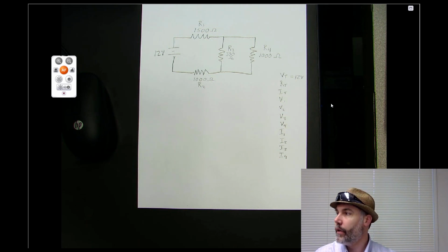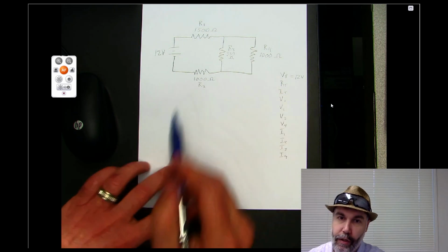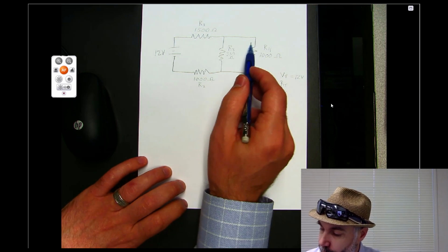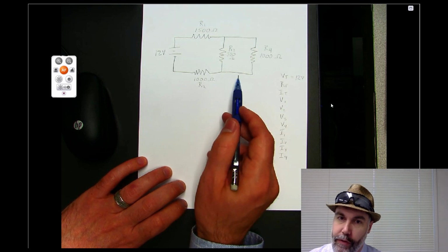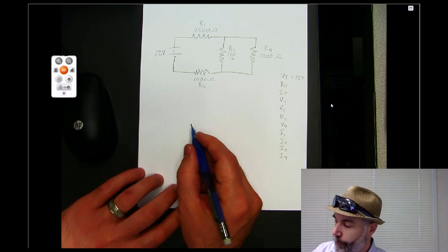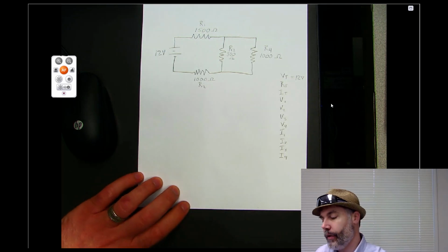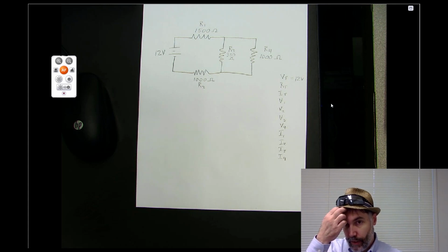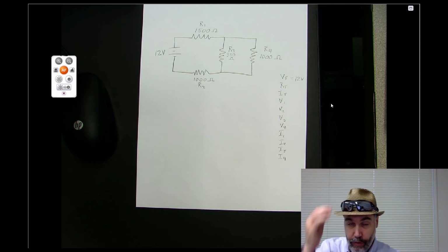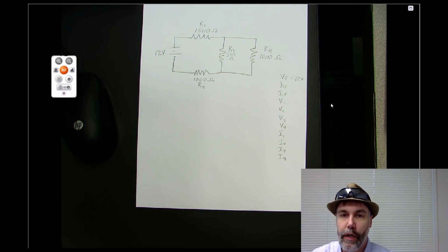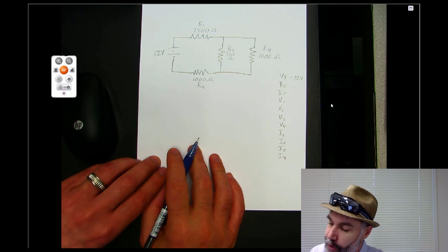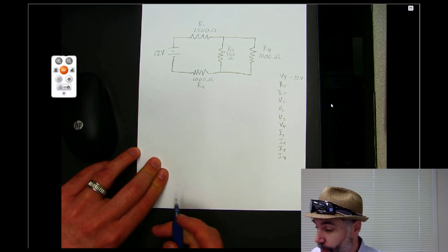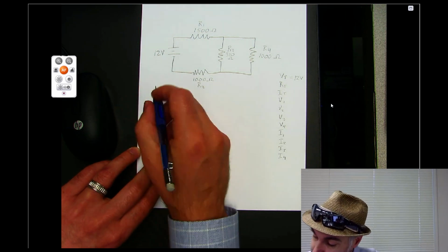Okay, do you see any resistors that are in series or in parallel? R3 and R4 in parallel? Yeah, that's right. R3 and R4 are in parallel. We can tell because the beginnings of those resistors are connected to each other with nothing in between, and the ends are connected to each other with nothing in between. So we need to find their equivalent resistance. Can we just take one of those values and divide it by 2 since there are 2 resistors? No. We could do that shortcut if both resistor values were the same, but since they're different, we have to use that parallel resistance formula.